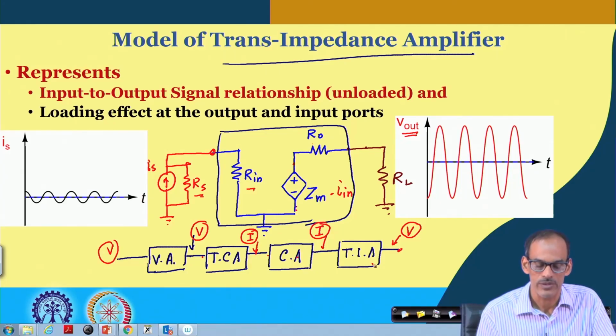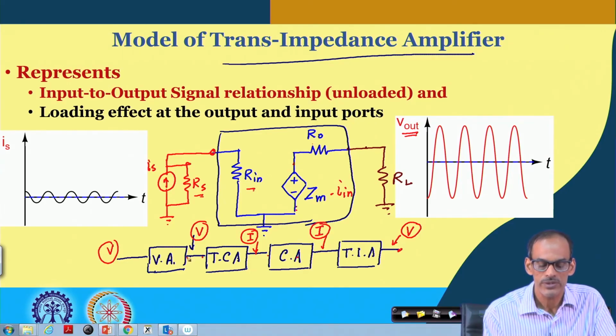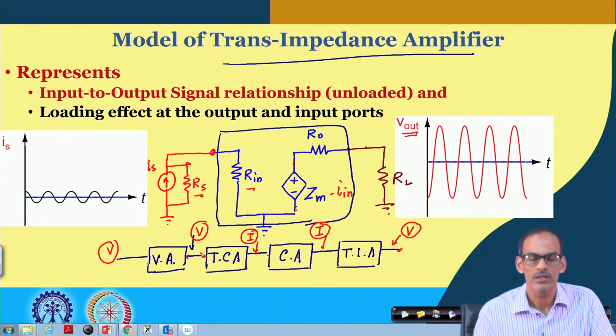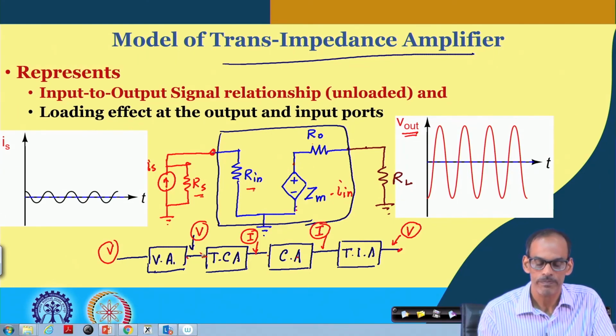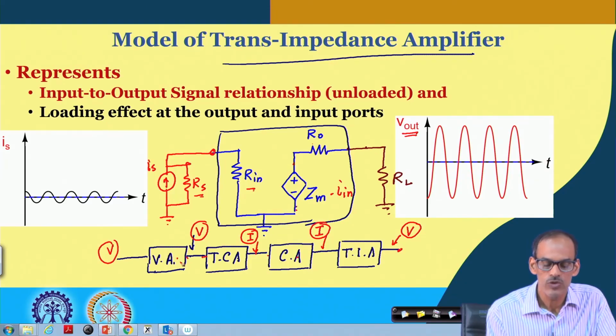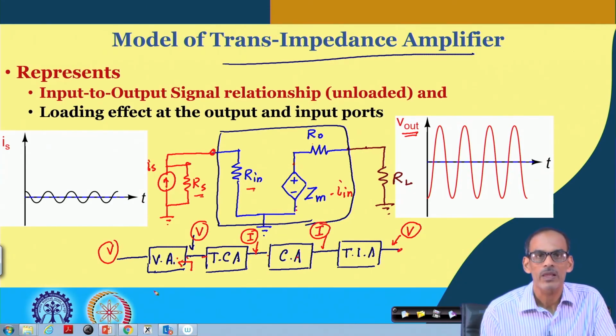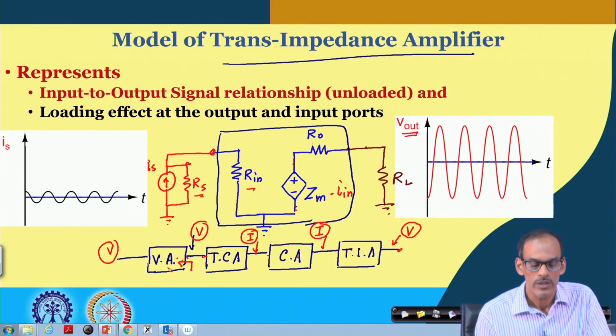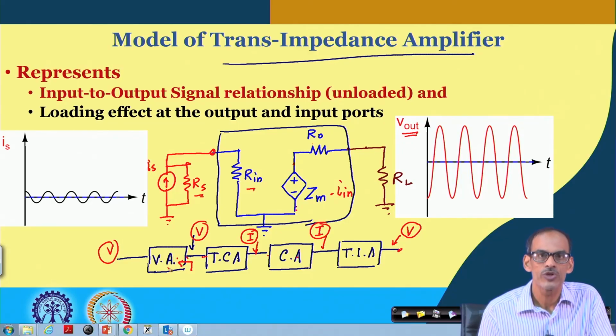So, we may have a chain of amplifiers where each of the stages is a different type of amplifier. Now, the natural question is: if the signal here and the expected signal at the next stage are not consistent, then what do you do? Luckily, each of the stages has its own practical output impedance or output conductance element, and you can convert the output port model into the appropriate model, namely Thevenin equivalent model into Norton equivalent and vice versa.